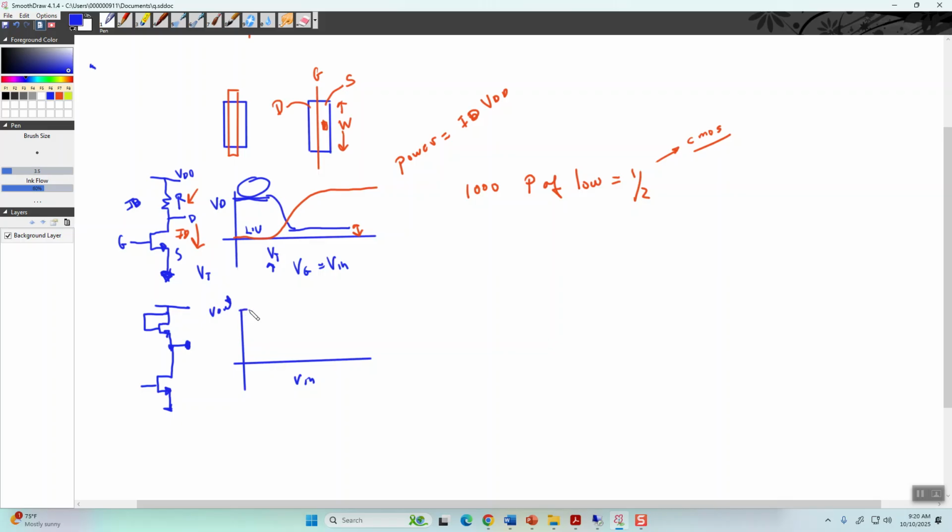So let's call that VDD, but you need a threshold voltage to turn it on. And because the body and the source are not at the same voltage, the threshold voltage is even higher. All right. And that would be gamma in your SPICE simulation.